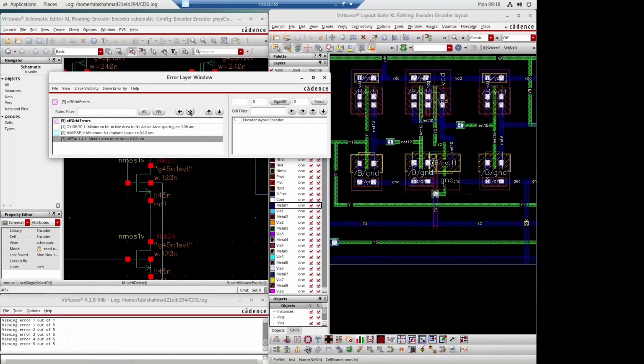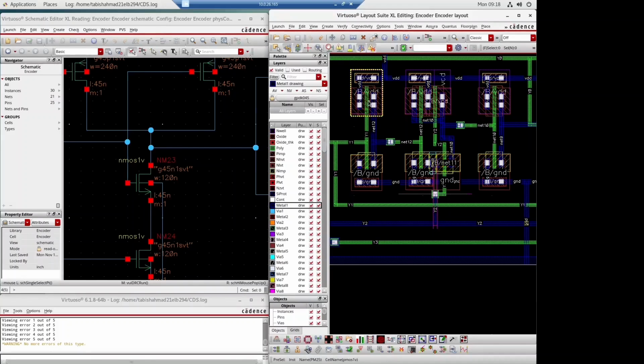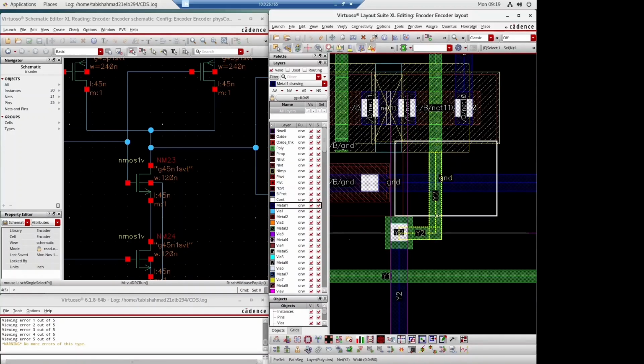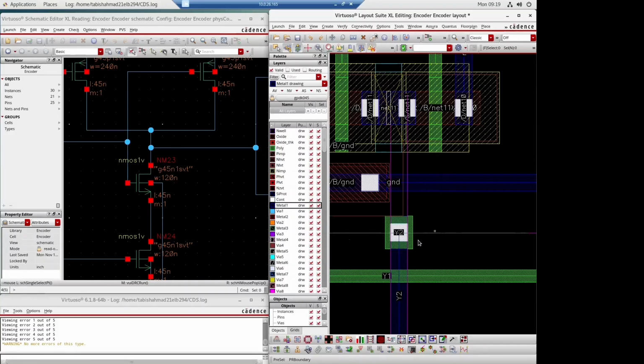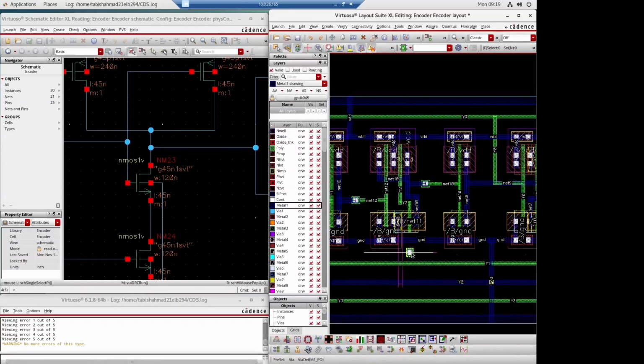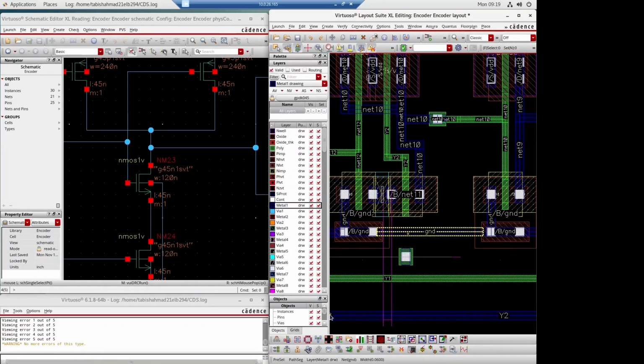What we can see is we have reduced the metal one errors that were 8 previously, now they are 7. So this overlapping is now correct, but due to the new errors we have to correct the remaining things that are getting disturbed. These purple lines on the Y2 metal, and this polysilicon line, are indicating the error. So what we'll do is move the via right under the polysilicon, and remove this metal connection. We will place a straight connection of polysilicon with the via.